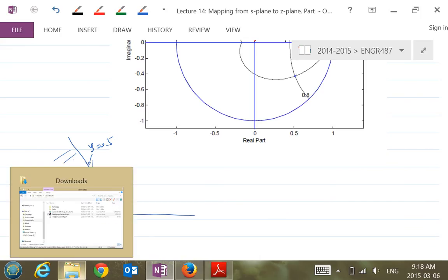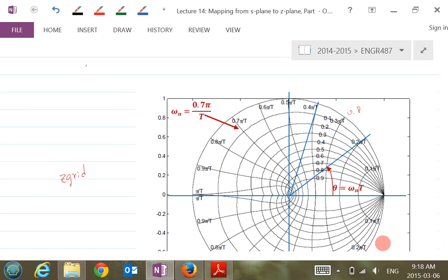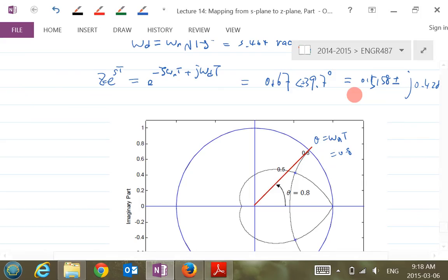The 2 constant damping ratio lines. If the boundary is this, you want your damping ratio to be less than 0.5. Then where should you be? Should you be outside this or within this heart? Within the heart, right? Because you see those damping ratio lines here? What's the trend? As it goes out, it's getting smaller, right? Getting smaller. So you should focus on this inside here.